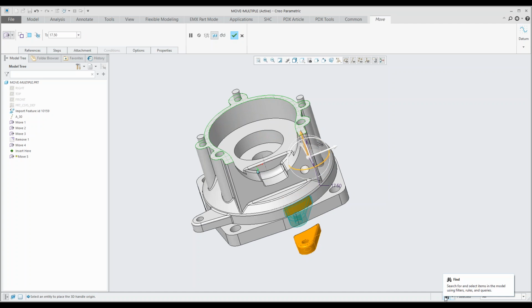It's not showing anymore. But next to this, to the find icon, there's like a stop sign. Let me just see if I can get that. So there's the stop sign now. So if Creo is going into a loop, you can just hit that stop and it will basically take you back to the last solution it had for that particular geometry, or it will cancel the movement that you've applied. Okay, so that's when something goes wrong or Creo goes into a loop. Just stop it. Yeah, at the bottom in the message window.